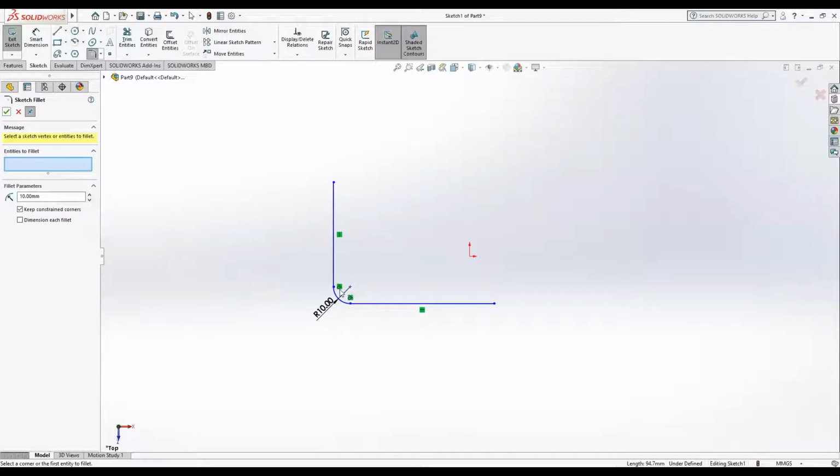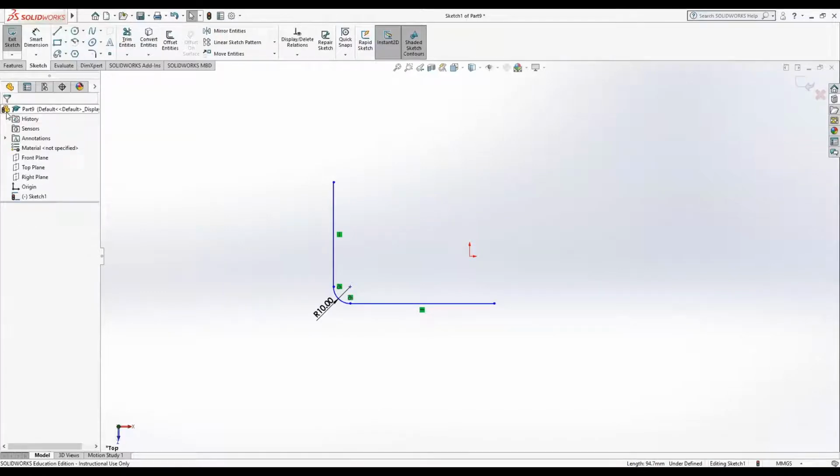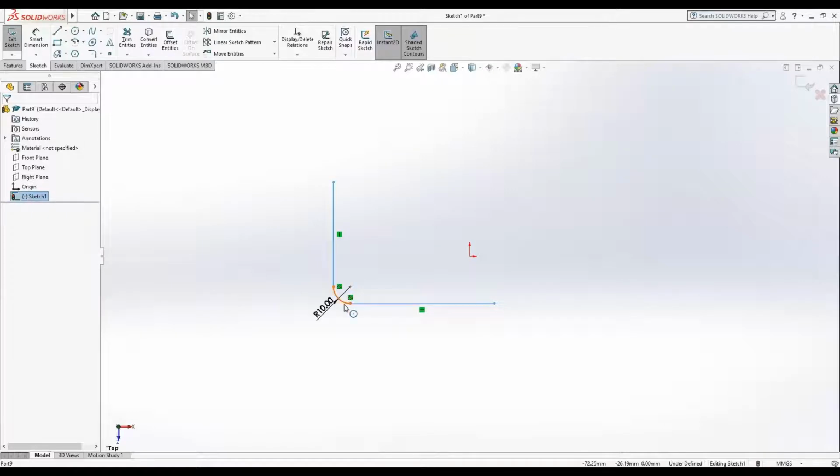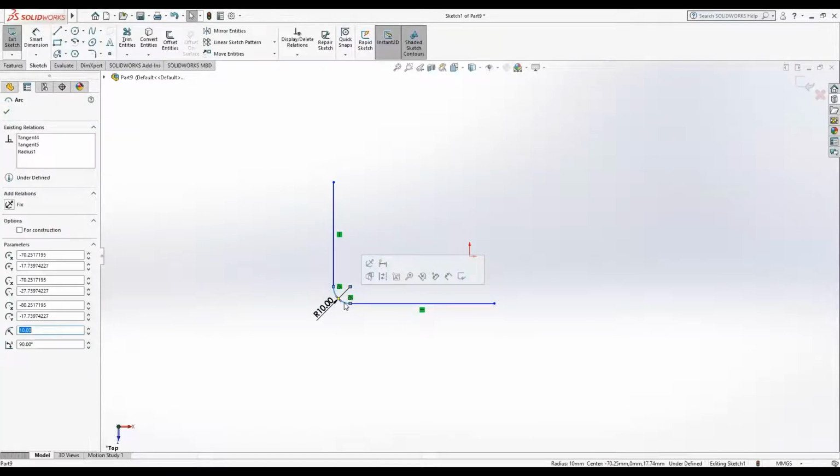It gives you what your radius is. It has a start point and the end point are on tangents there. Some of the things you can change in here are how big it is. And once you've done this, you can actually click back in and you can change where your start end points are for your coordinates, your center point, and what your radius is here.